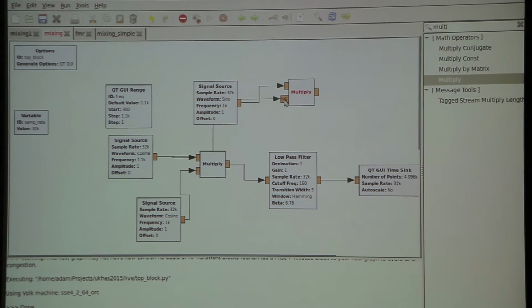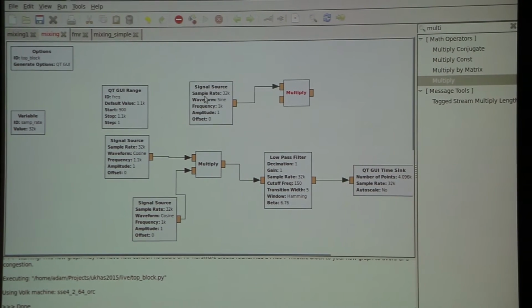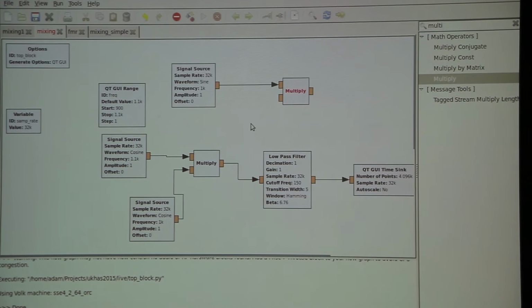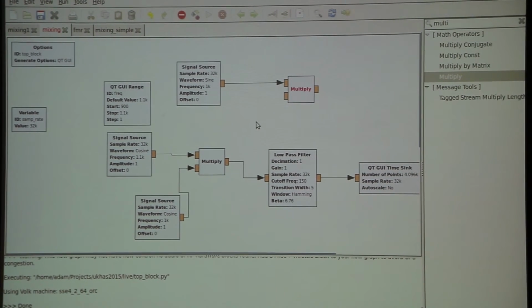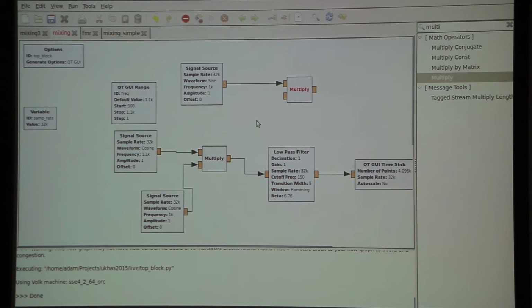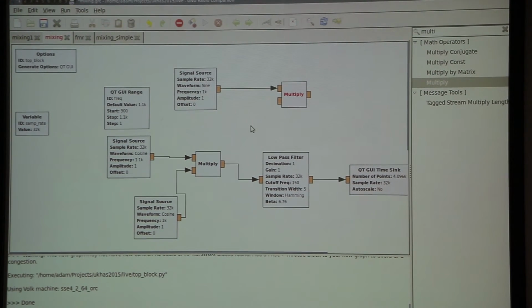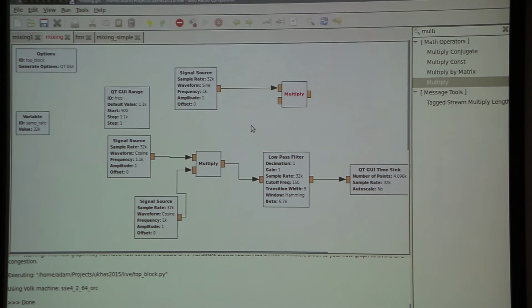Can I just ask, why is it called the multiplier when it's actually adding and subtracting? Yeah, absolutely. At a voltage level, the actual signals you see, it is multiplying. It adds and subtracts in frequency. Oh, okay, so it's the amplitude that it's multiplying and the frequencies that it's adding. So I could try and illustrate it. If you have two sine waves and you multiply the values together at every point in time and they're slightly different frequencies, what you get out is a kind of messy wave that has two different frequencies in it.